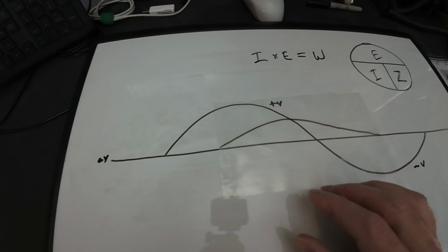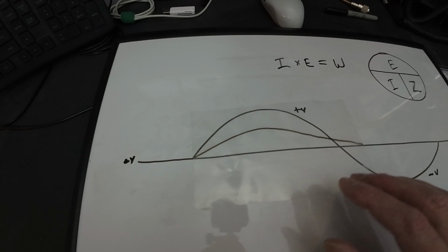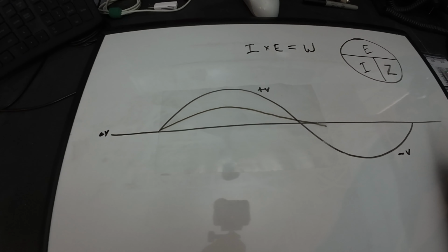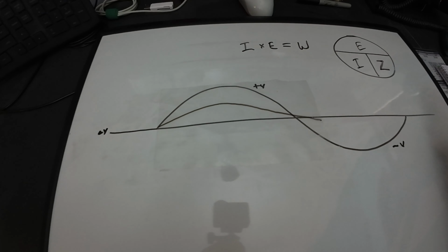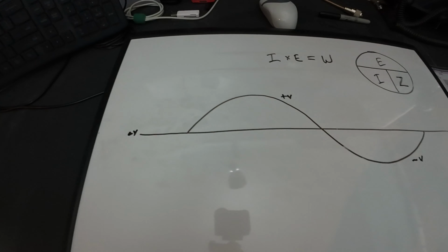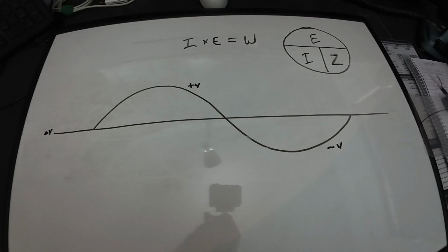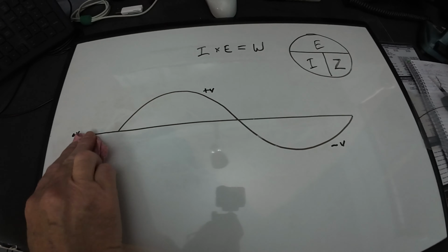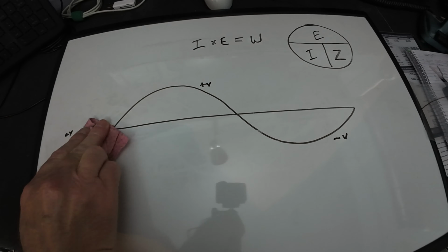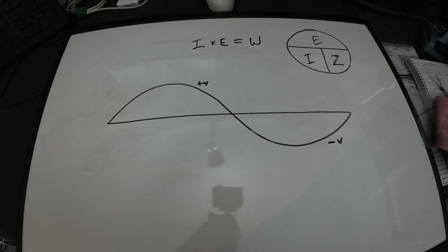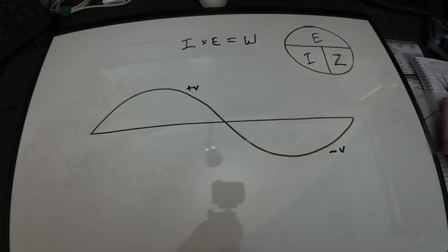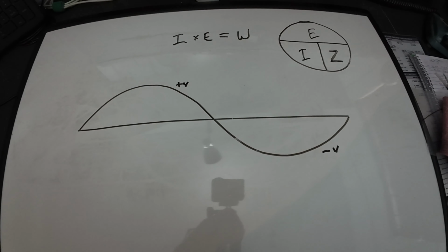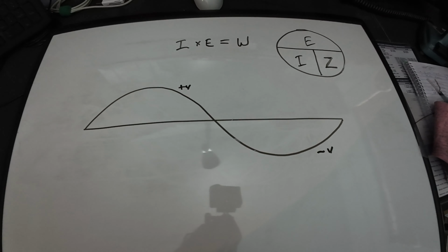If these elements aren't in phase, we don't have the correct impedance on the transmission line. It's going to be off. So let's pretend that this is a 67-foot piece of coax. We're staring at it from the side. And we're transmitting a 14 megahertz signal into that 67-foot piece of coax. There's a full wavelength of RF on that piece of coax.